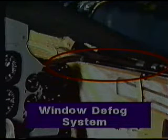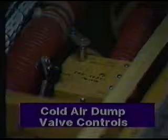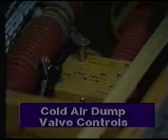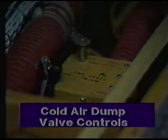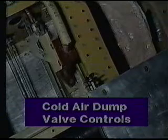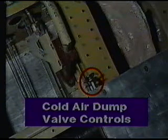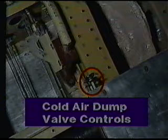Air routed to the cockpit windows is part of the window defog system. Units that allow the dumping of the cold air supplied to the eyeball fittings are called the cold air dump valve. The handles located near the co-pilot's seat for controlling these valves are called the cold air dump valve controls.